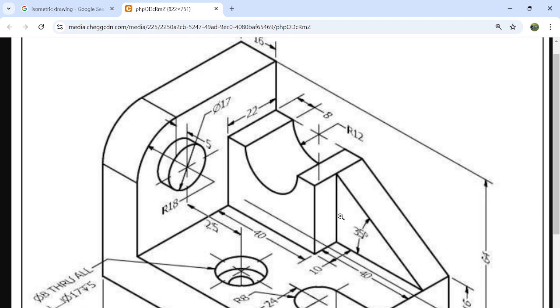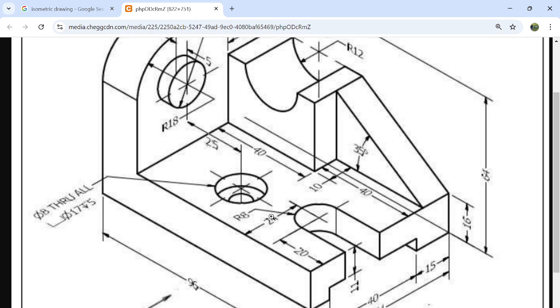Then for the next sketch, what we have to do, we have to draw this smaller hole of 8 diameter. Simultaneously we will draw this profile. Okay, and because it is also a through one, simultaneously you can pocket that surfaces. Okay, so in two sketches these two will be completed. Okay, for this one sketch, for this larger one, this smaller, and this one, the second sketch. Okay, so we'll start with this.